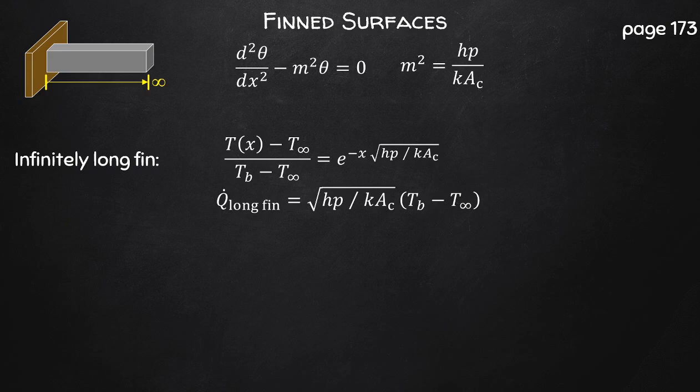So just remember that we apply this equation for fins whose tips are close to that of the surrounding fluid temperature. So if the fin's tip is kind of close to the temperature of the fluid, then we're probably dealing with an infinitely long fin. So the fin doesn't need to be infinitely long.